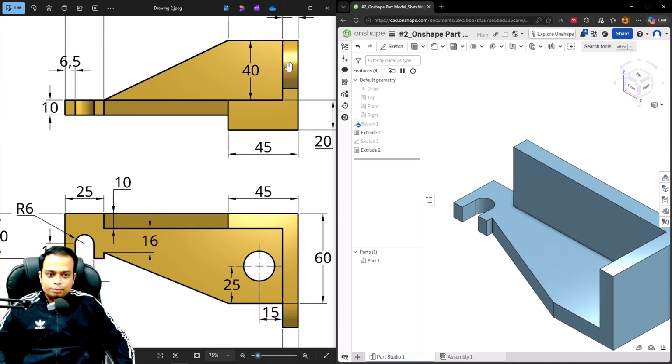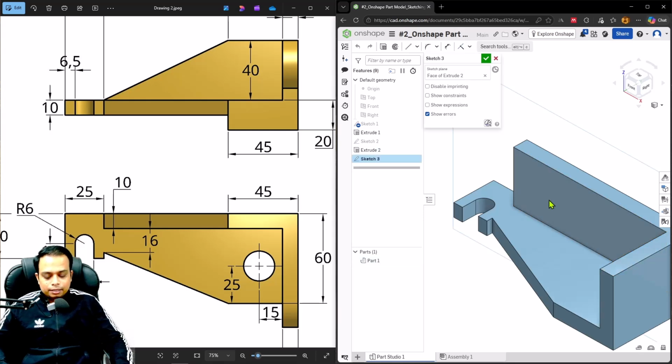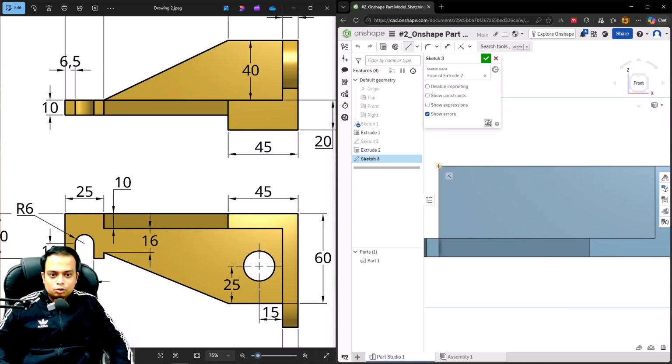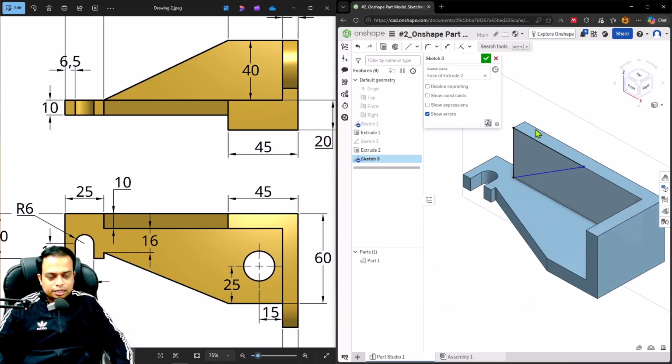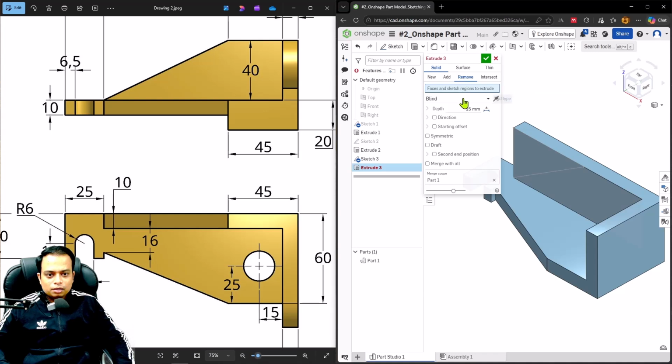Okay, now I am going to make a triangle, this triangle over here, and then I am going to use the extrude removal feature. So for that I need to select this. I need to make a sketch, hold shift, and I am going to go normal. Okay, now use the line command to make a line in this fashion. This way, this way, this way, and this way. Shift 7. Okay, wonderful. Escape, and now use the extrude feature, shift T, cancel this, removal, go for through all, and I think I have to select this bounded region.